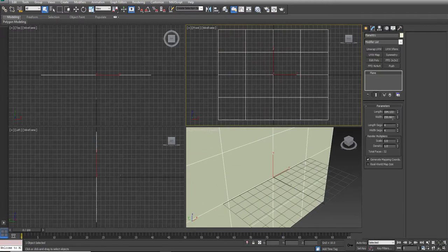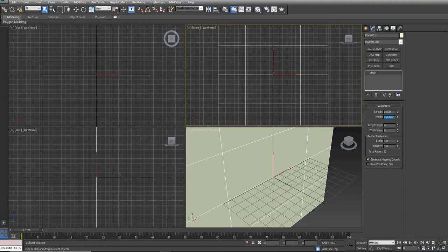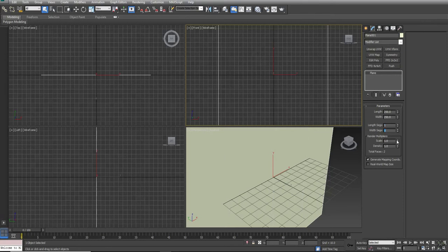And once I've created the plane, I'm going to go to Modify and square off the values, and set length and width to 1. I'm just hitting Tab to go between the different portions. I'm going to come up to Move now, and I'm going to center my reference plane.